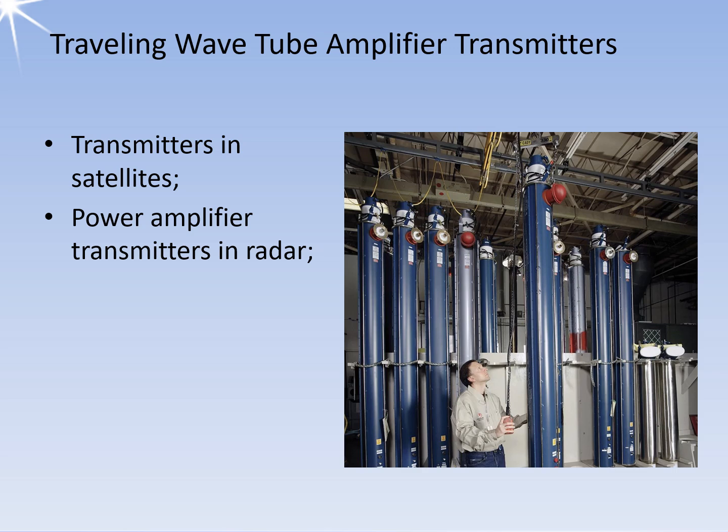Traveling wave tubes with coupled cavity slow wave structures are used as power amplifiers or as preamplifiers for high power transmitters with crossed field amplifiers or amplitrons. They have significantly higher output power but a lower bandwidth of 10 to 20%. The figure shows some of the total 128 coupled cavity TWTs used in the AN/FPQ-16 radar in North Dakota operating in the VHF band.